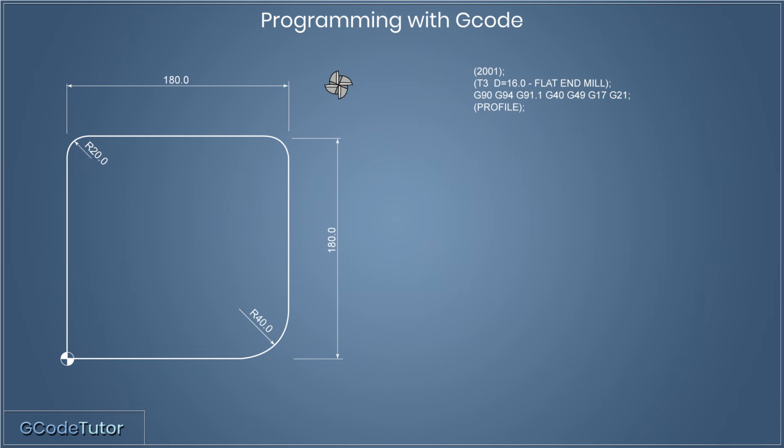Our first M code that we come across in this program is M05. This just tells the machine to stop the spindle. There's a very good chance the spindle is already stopped at this point, but if it is running, it will stop it now so it's safe before we start running the rest of the program. Now all M codes and G codes that start with a 0, we can omit the 0, so this can also be written as M5 and the machine will read it just fine. M09 is our coolant off M code, so if the coolant is on, it will turn it off at this point. If it is not on, it will just skip this line and continue reading the rest of the program.